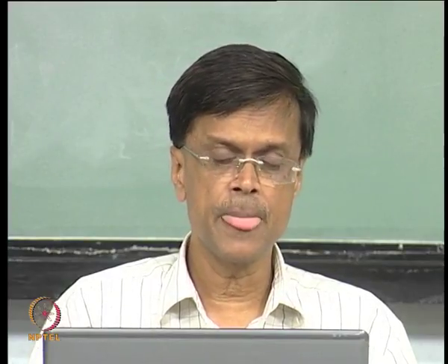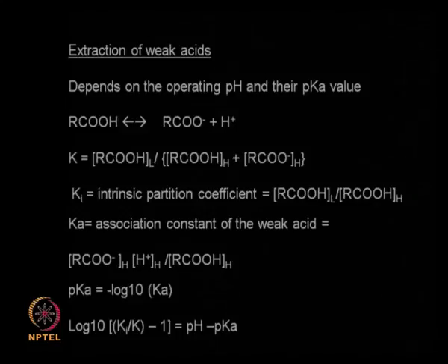The main disadvantage of cross flow is that every time you have to add a fresh solvent, that means the solvent usage is going to be very high, whereas in the countercurrent design the solvent which is leaving stage 1 will enter stage 2, that way you are not using too much solvent unlike the cross flow design. And the equations for the countercurrent design change when compared to your cross flow design, we will look at it later, but before that we will look at something else.